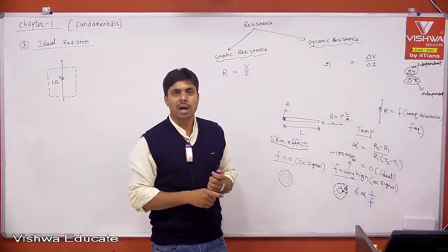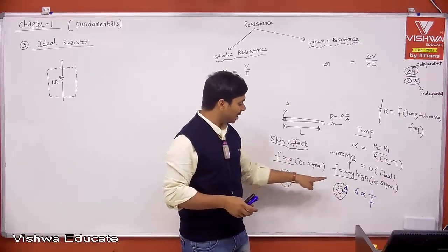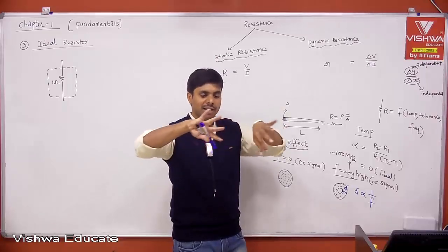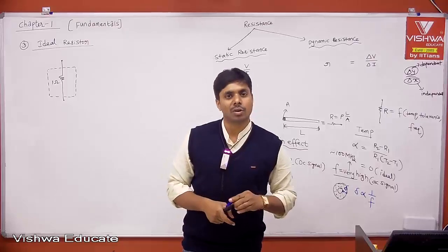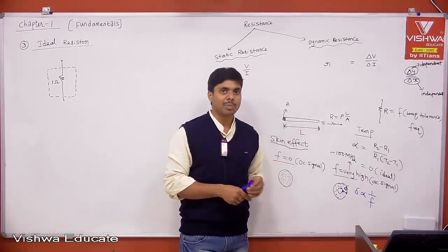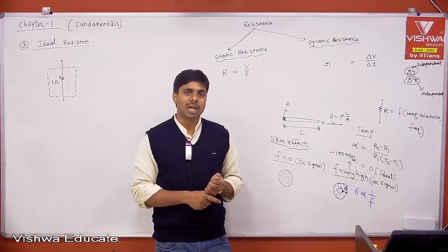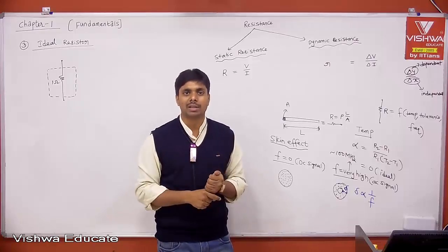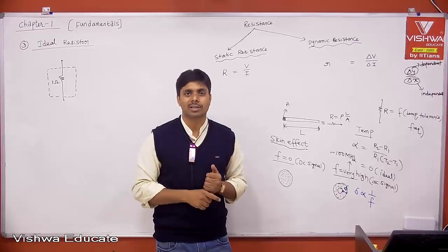What is the disadvantage? If the carriers are concentrated to the skin of your conductor, coming towards the surface, then the collision between one electron and another will increase. If the collision increases, then the mobility of the carrier decreases, meaning your current is decreasing, because rate of flow of charge is nothing but current. In a given time, the charge movement decreases due to mobility decrement or collision increment, so current decreases for the same voltage.